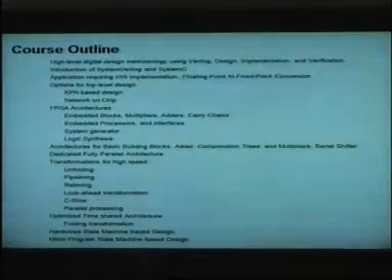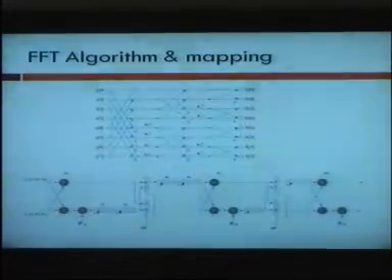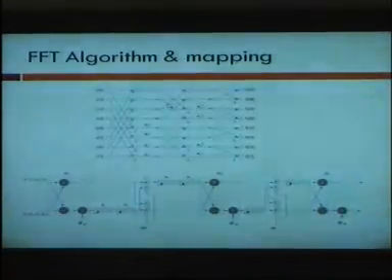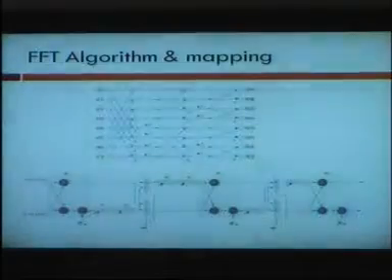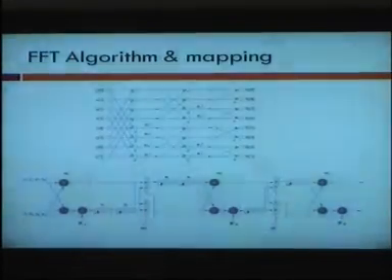The fully parallel means that the way you draw it, you actually implement it in the same way. So the easiest to design is this: the algorithm description in a flow graph. Just do the same in hardware. Wherever there is an addition, you put an adder. Where there is a multiplication, a multiplier, and many people try to do this.